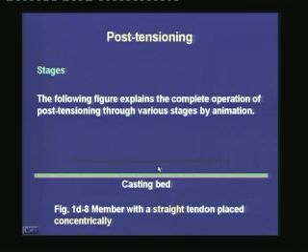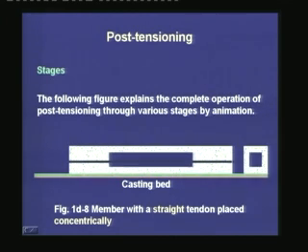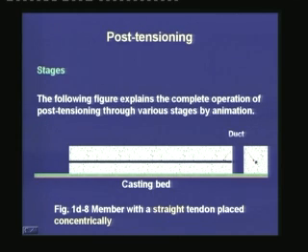As I said, in post-tensioning, the casting bed need not be like a pre-stressing bed in the pre-tensioning system. The casting bed is just like any other ordinary casting yard, and after the mold is placed, the concrete is cast with an annular space inside.